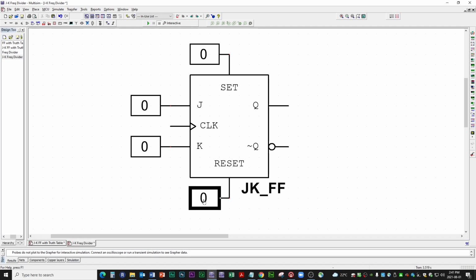So when both inputs, reset and set, are sitting at or tied low, which means if they're active high, they are not high, they are going to basically be almost as non-existent as far as functionality. They are going to let the synchronous inputs take over the whole operation. All right, now we're going to have to establish something that's called a toggle position.